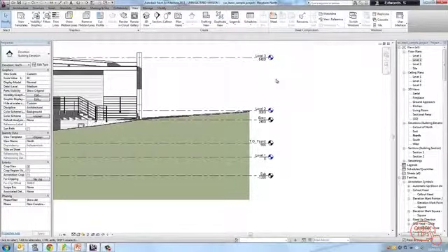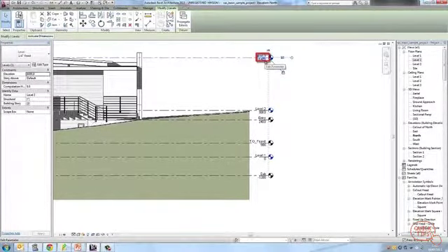First of all, I'm going to modify the height of level 3. To do this, I need to click the level line to highlight it, and then click on the height parameter. A new editor box appears here. This is the height parameter, this is the elevation.